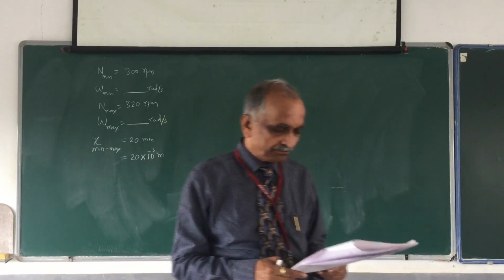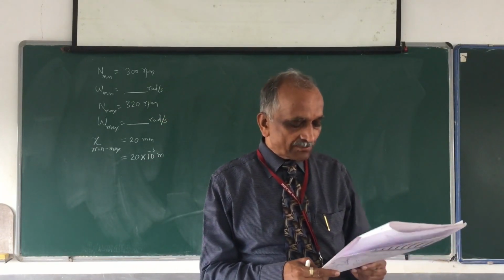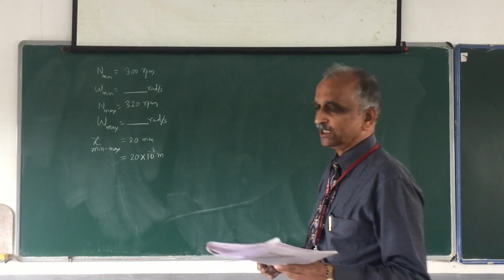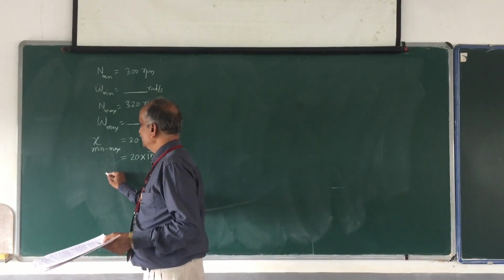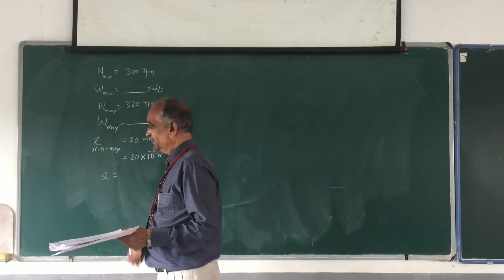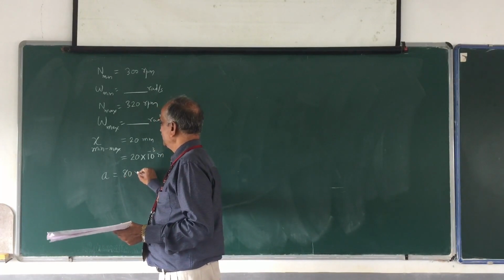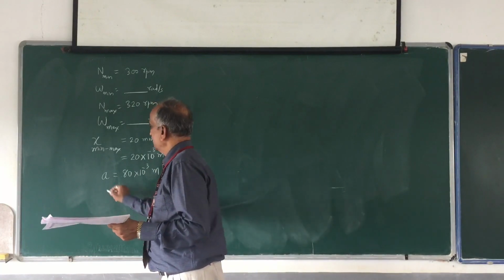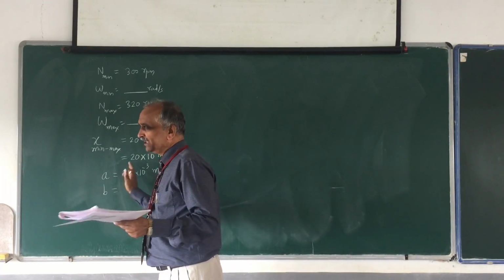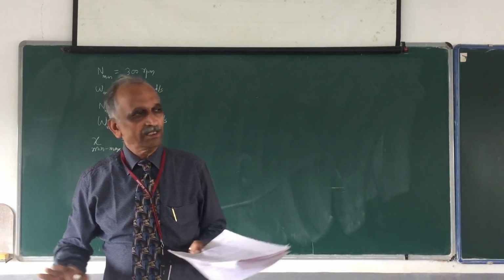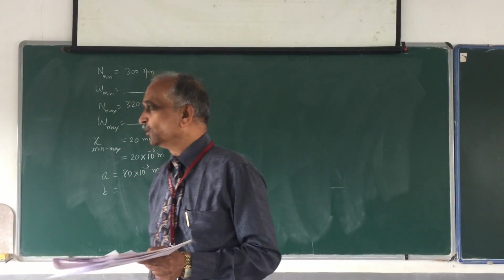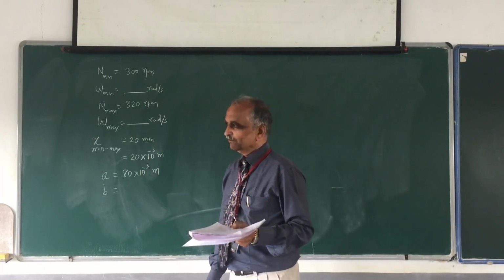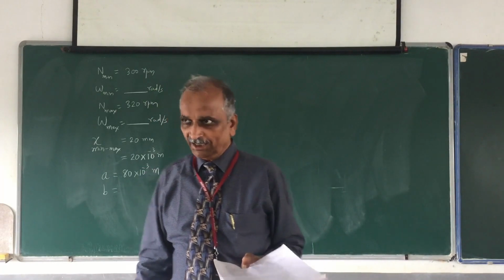Okay, the next information. The sleeve arms and ball arms are 80 mm and 120 mm respectively. So sleeve arm we are referring to by small a, 80 mm. So again 80 multiplied by 10 raised to minus 3 meters. And if you are quite confident, I don't mind you continuing these values in millimeter, but I don't wish you to make any kind of mistake.